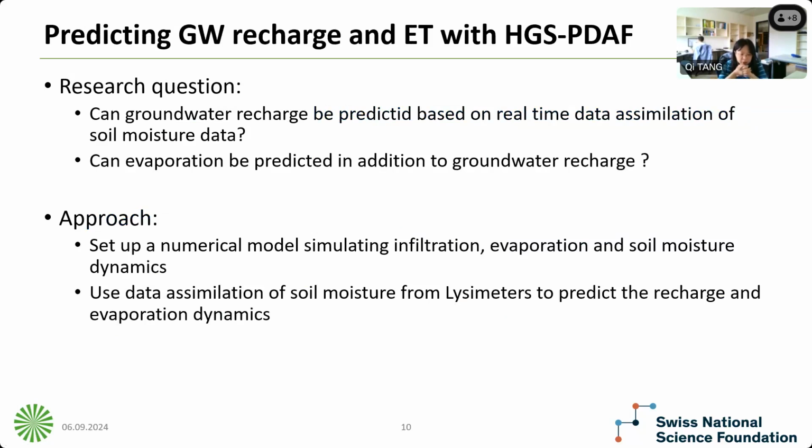Next, I'd like to show another application case. They started to explore whether groundwater recharge can be predicted using real-time data assimilation of soil moisture. And we also aim to explore whether we can predict evaporation as well, together with the groundwater recharge. To address these questions, we set up a numerical model which can simulate infiltration, evaporation, and soil moisture. And we use data assimilation by assimilating the soil moisture data from the lysimeters to predict the groundwater recharge and evaporation.